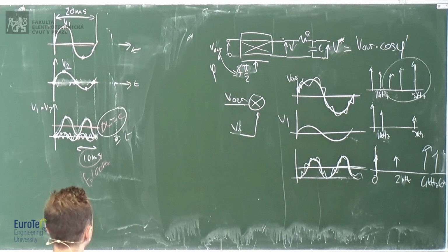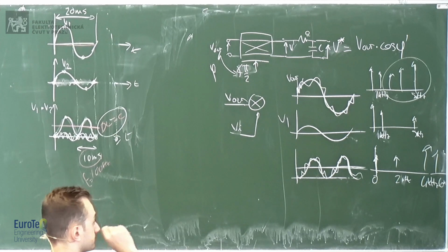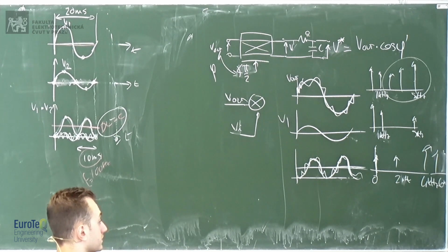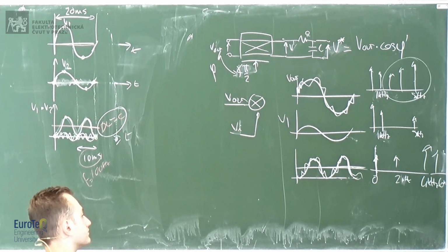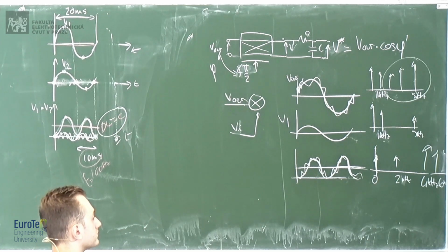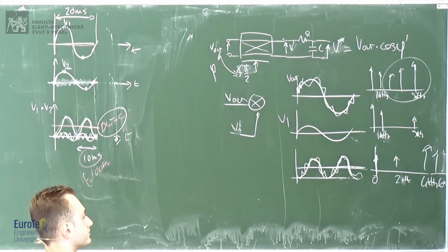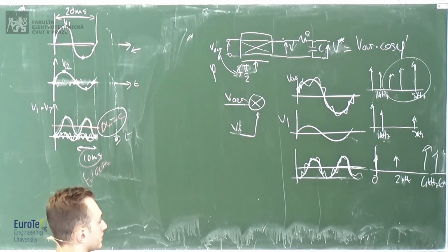The point is that multiplying two signals is not so easy. If you watch all the analog multipliers, the noise is quite large. So theoretically, this is a nice system, but then you should always go and check in reality what the numbers are in terms of noise, because sometimes it's just better to use the flipping system when you go down to the numbers of the noise. In theory, it's better. In reality, very often it's just better to use the flipping system.